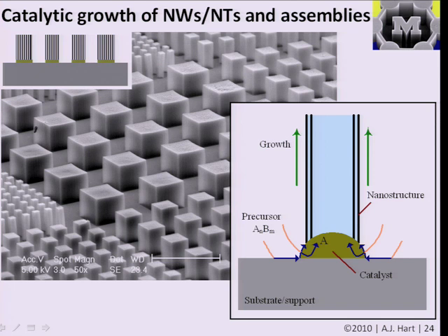But the growth process here is essentially proceeding at the atomic level and relying on the fundamental interaction between the precursor and the substrate and the catalyst, and how it then organizes to build this nanotube at the atomic level. For example, how well we control the sizes of these individual particles determines roughly the diameters of the nanotubes that are made. And for example, how the particles evolve with time as the growth process proceeds.